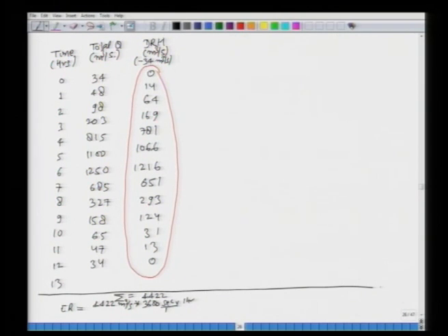And then we divide this whole thing by the area of the catchment, which is 796 square kilometers. We need to convert it into square meters. So, you multiply by 10 to the power 6, this is square meter. You take care of the units, and then you multiply this whole thing by 100 centimeters in a meter. So, this will come out to be approximately 2.0 centimeters. So, this whole runoff hydrograph ordinates they result from 2 centimeter of rainfall.